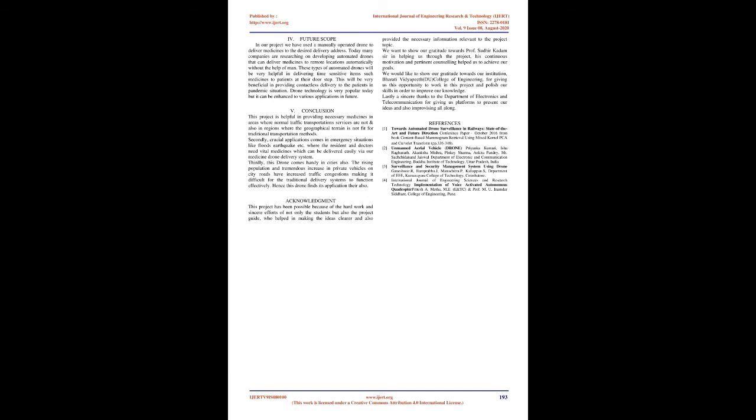The general configuration of a quadcopter drone is 2 clockwise propellers diagonal to each other and 2 counterclockwise propellers diagonal to each other. G. Battery. The battery provides power to the drone. We have used a rechargeable lithium polymer battery, LiPo, of capacity rating 2200 mAh. Lithium polymer batteries have high energy density in relation to their size and weight, with a higher voltage per cell.